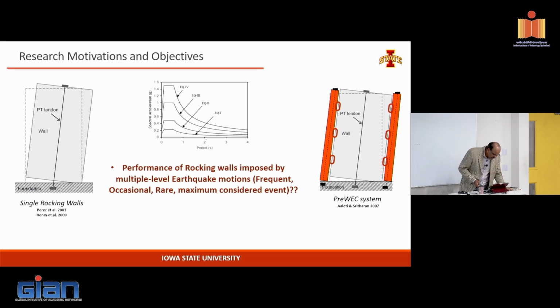What is it called? Yeah, EQ3. That is what we typically design for. It's known as the design level earthquake. And then the EQ4 is the equivalent of the maximum considered earthquake. So if you're doing a performance-based seismic design, you'll be designing it for both cases, one for the design level and one for the maximum considered.